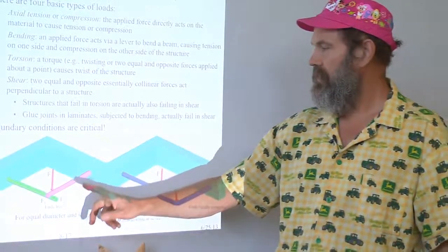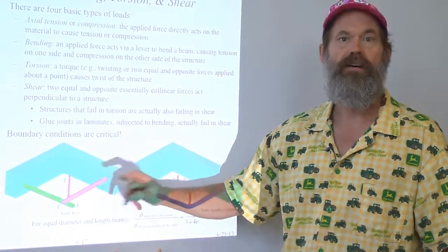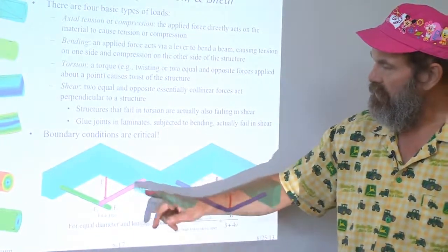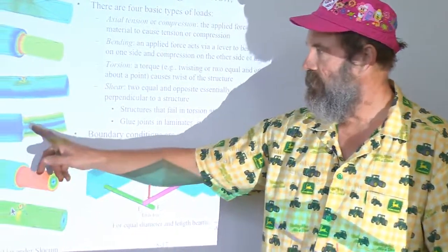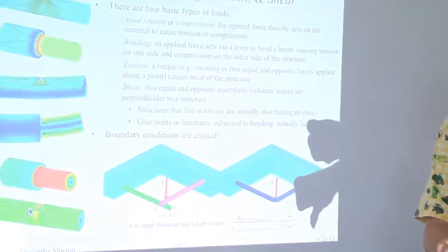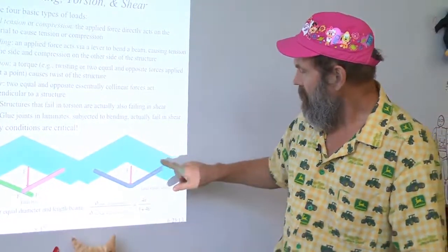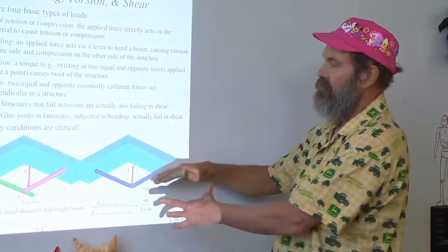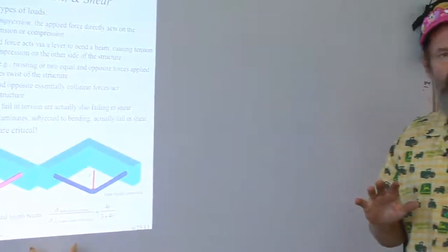The stiffness and strength of joints becomes an issue to be wary of, in particular the strength issue, when you have stress concentrations wherever you have a physical joint between things and a discontinuity. When I form something, I can often put a nice, big, gentle curve in it, which can help to reduce stress concentrations.